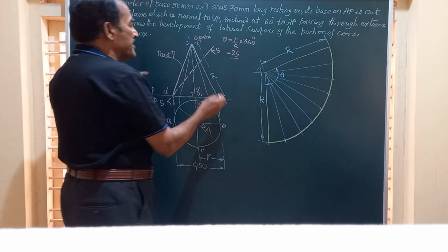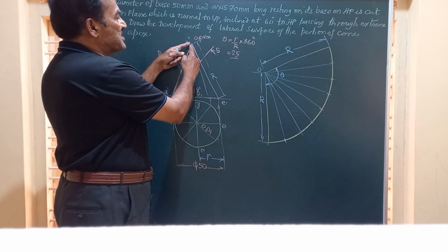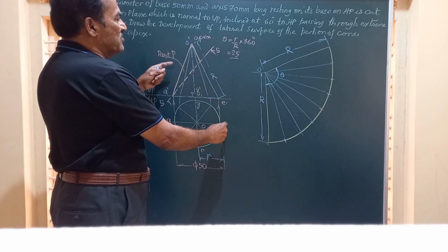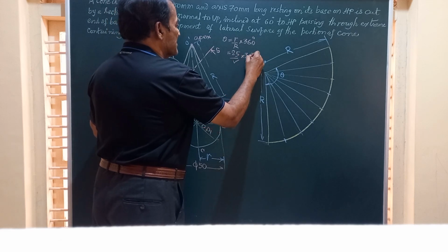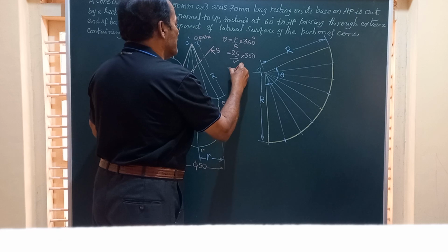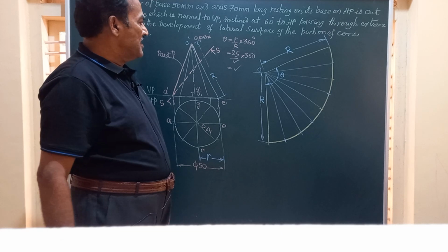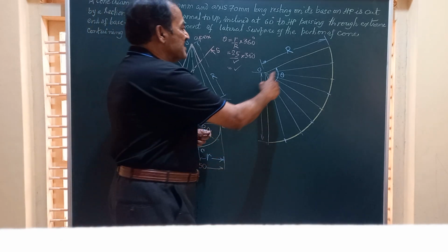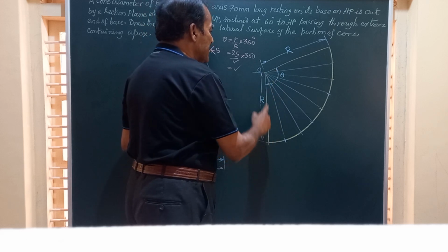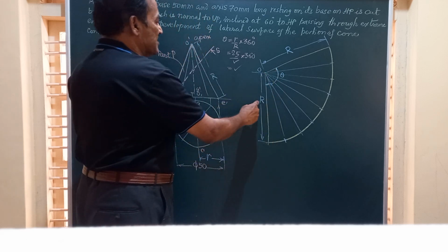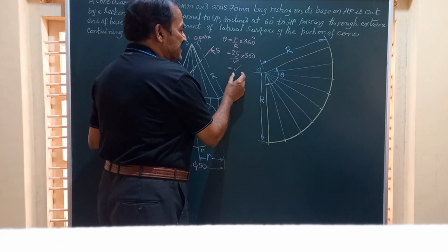And this can be obtained only after construction of this triangle in the front view. Keep a scale between O dash and A dash, find out its length. So this can be obtained, multiplied by 360. So you will get some angle, which I have marked as theta. Now friends, after this, we have to mark this sector depending on this value. So we have to draw a vertical line of length equal to the true length, that is R, and draw that circle or sector having angle theta.